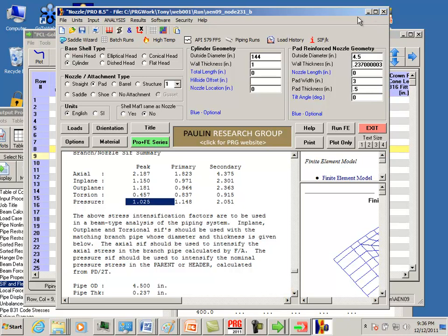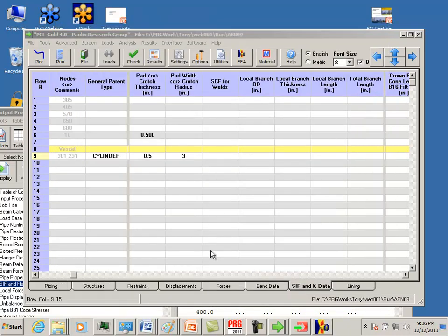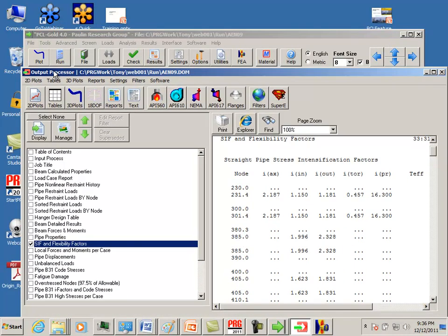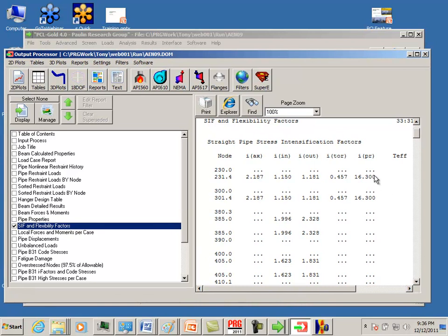If we make the same calculation using the B31-3 nominals, we get a pressure stress intensification factor of 16. So it's very important when we use pressure stress intensification factors and try to get applicable data from other sources that we make apples to apples comparisons. That's one of the reasons that I wanted to go through this here, because these high numbers sometimes cause alarm, but when you look at them in terms of the nominal stress basis, this makes perfect sense.